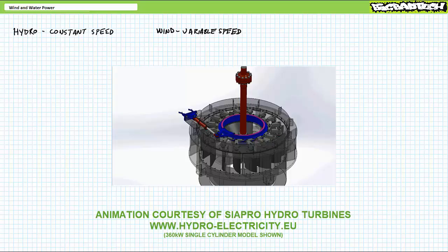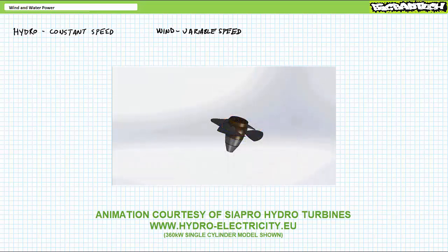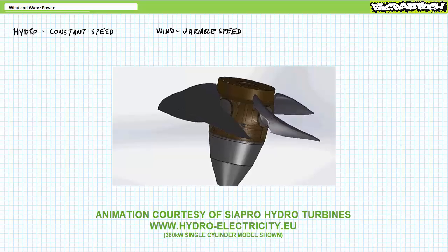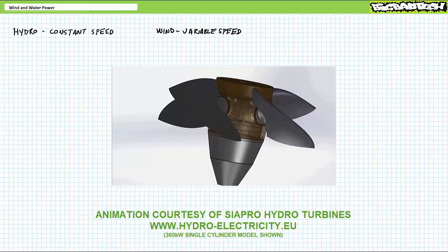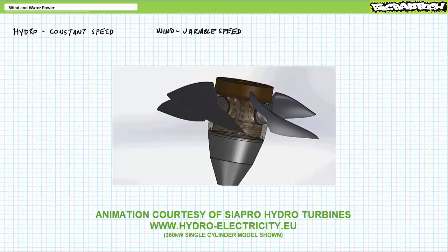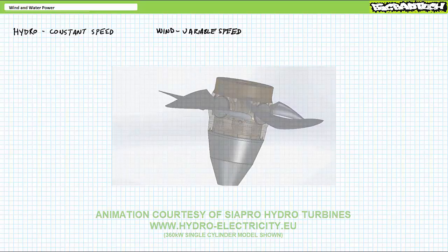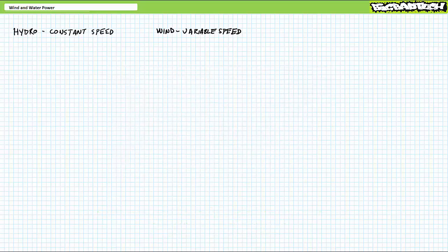In addition to modulating the flow rate using the wicket gates, a Kaplan turbine can additionally pitch the blades, as do wind turbines, to capture more or less of the incoming flow. If you think about it, the primary responsibility of a hydropower turbine control system is not to respond to wildly changing input, as would a wind turbine, but rather keep input inside a defined range that maximizes efficiency. The logical extension of this different means of control has some pretty important consequences to the methods one uses to generate power from wind versus the method one uses to generate power from water.